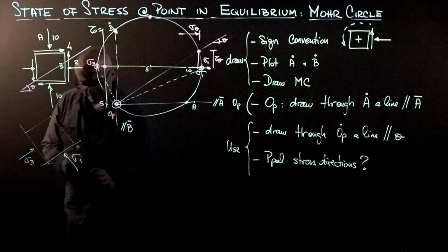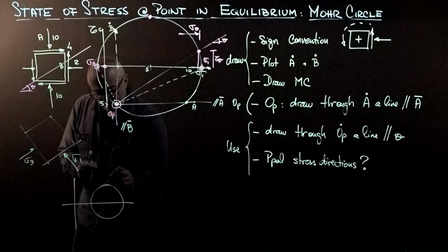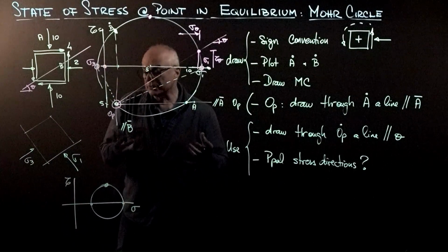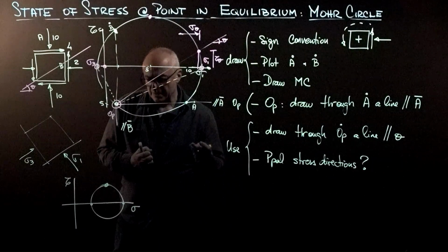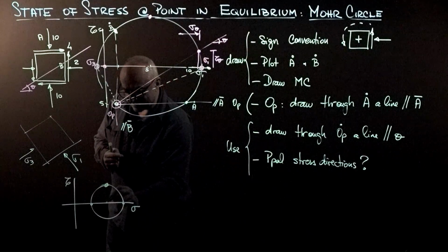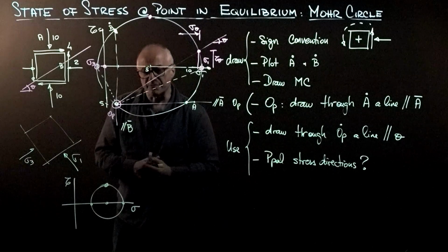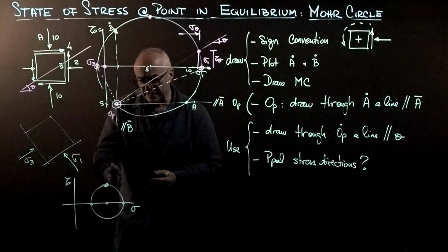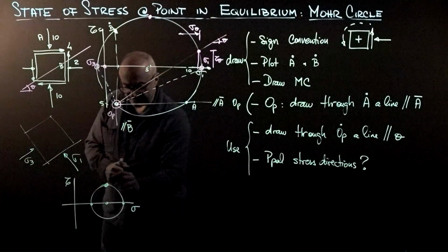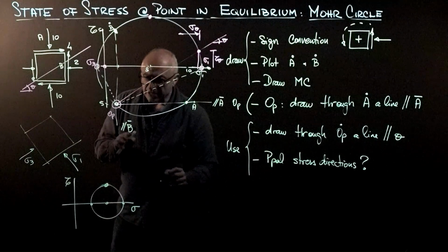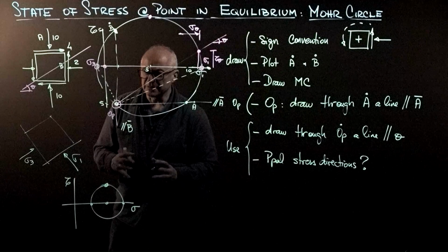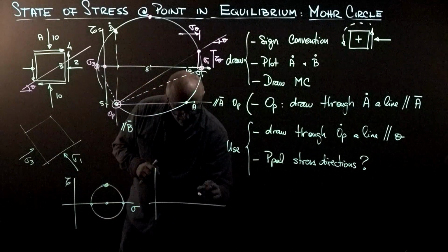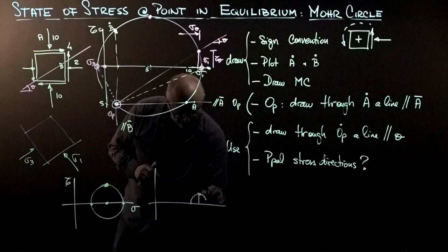One final observation. If you have a Mohr circle, the position of the apex is totally descriptive of where the circle is. I mean, in order to define a circle, you need 3 parameters. In this case, one of them is known. It's going to be at the center beneath the apex, and it's going to be centered on the tau equals 0 axis. So that's one known. The other two are the xy position, the tau sigma values at that point. Therefore, I don't need to draw the Mohr circle every time because it can get very messy. I only need to plot the apex because knowing the apex, you can always go back, drop the line, and draw the Mohr circle.